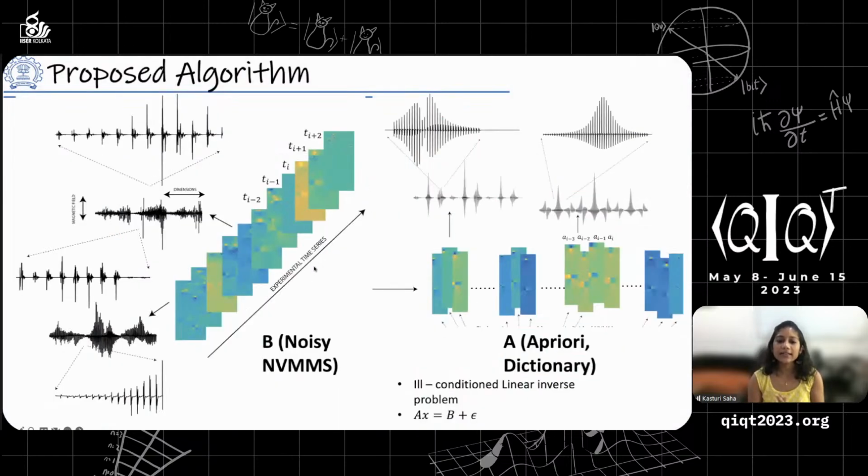Then the interesting thing that we developed is a method, an algorithm, which allows us to extract the locations of the neurons, using what is known as a matching pursuit algorithm. So we build a dictionary assuming that the neurons can be at a certain XYZ location in a voxel or a volume of material, and we estimate what magnetic field would be measured by the NV center. Then you use the NV center to measure a whole bunch of signals, which is essentially a vector sum of all the magnetic fields it would measure from different neurons that are firing.